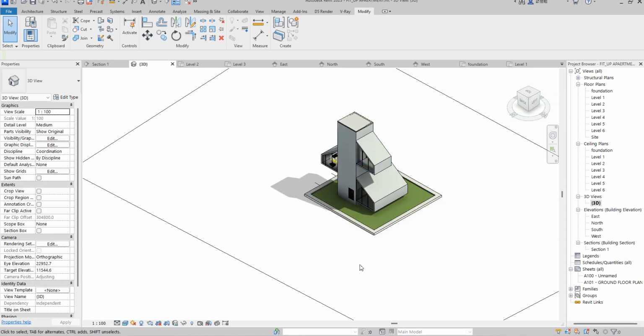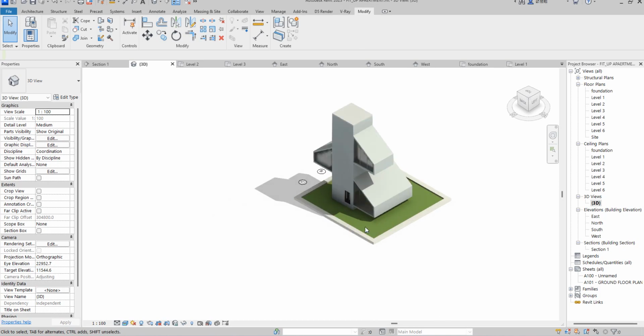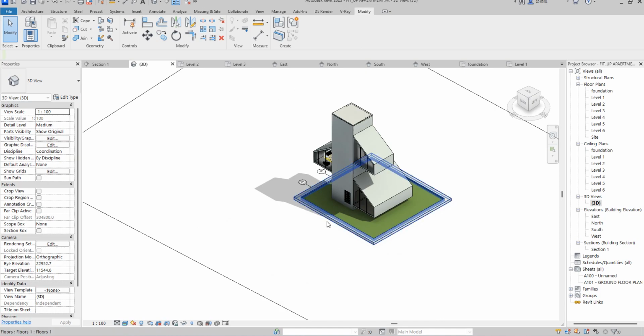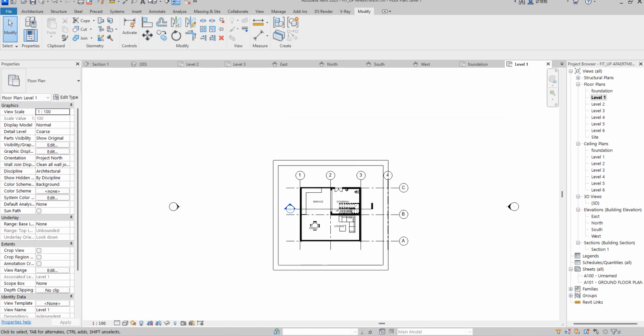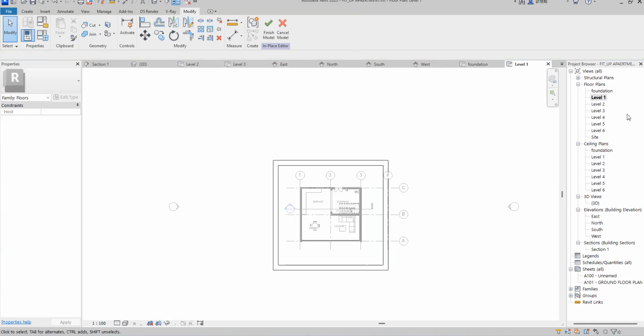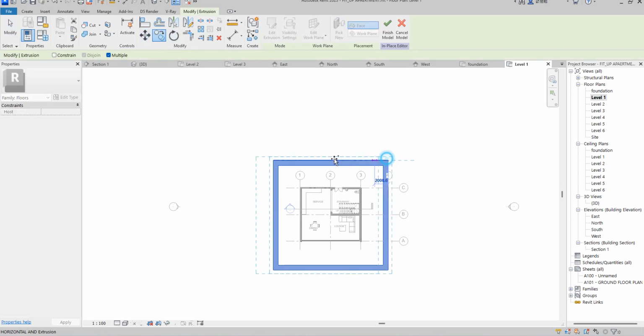Next thing you need to do is the pathway, so that when someone lands, you move from there, then walk through the house seamlessly. What I'm saying is, you can imagine this walkway around here. This is what we have created, and this is the walkway around this part. So let's quickly go there. We are still in the edit in place mode, and we still use the same component to do whatever you want to do. So now you click here. Let's say copy this.